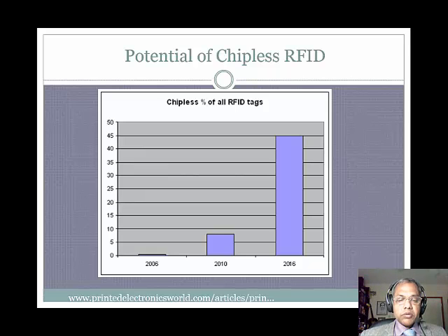Essentials of chipless RFID. This is an old prediction by IDTechEx that about 40 to 60% of the tag market will be occupied by chipless RFID tags. However, this is still a dream due to the technological difficulties and the cost associated. The only commercially successful chipless RFID tag is the radio frequency surface acoustic wave tag. However, RF SAW costs about $2 per tag due to special fabrication processes and SAW materials. It is non-printable and bulky.